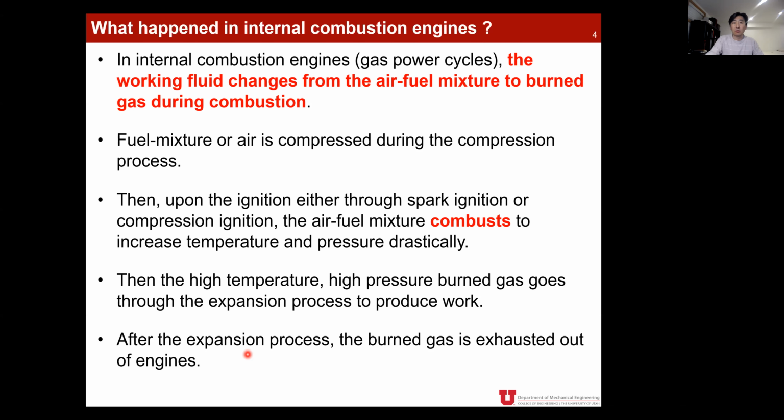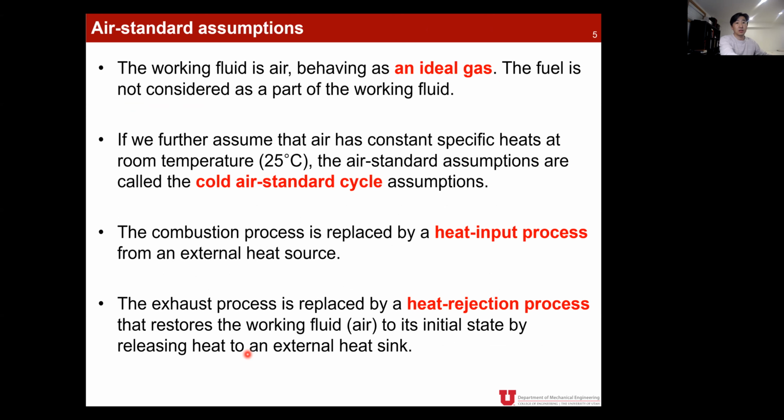So now we should talk about the air standard assumption. Again, what happens inside real heat engines is very complicated, so we want to have assumptions to simplify our analysis. Because we are dealing with gases like air, fuel mixtures and also burned gases, we assume all working fluid inside that type of gas power cycle is just air.